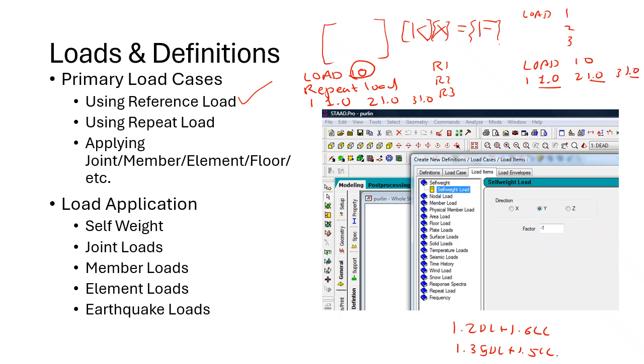So in this combination, if we have a truss member, the tension or compression force in a member, load case 1 he has solved, so he found some force F1. In load case 2, he found F2, and F3 for load case 3. So he will just give a mathematical addition, F1 plus F2 plus F3.